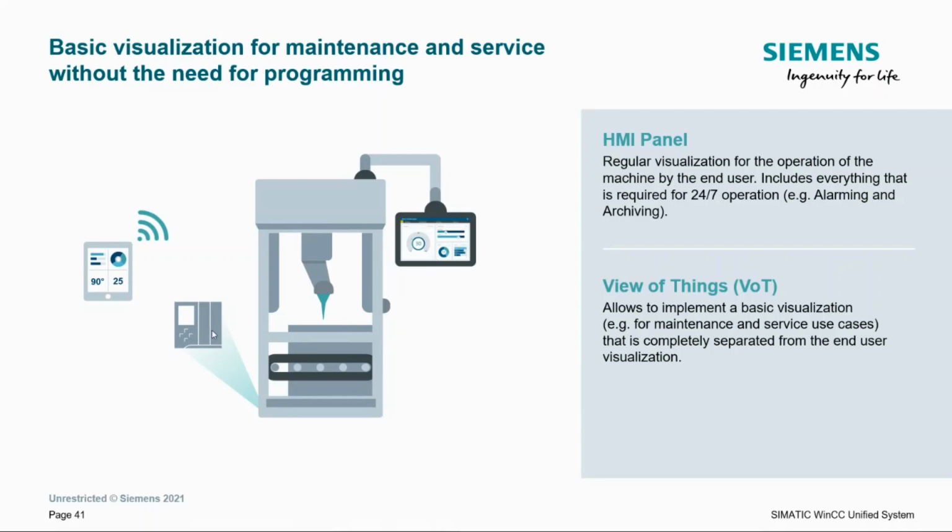What you can do is use the web server in the 1500. So now it has to be a 1500, any family of the 1500. So it can be the one we're looking at here, or the ET 200SP processor, the 1510 and 1512, or the open controller with the PC on it, etc. It can be used for this. So basically what happens is we build a website inside the processor with what you need for, let's say, some kind of calibration.